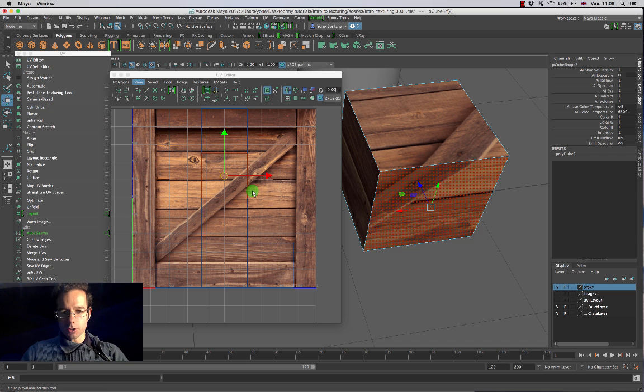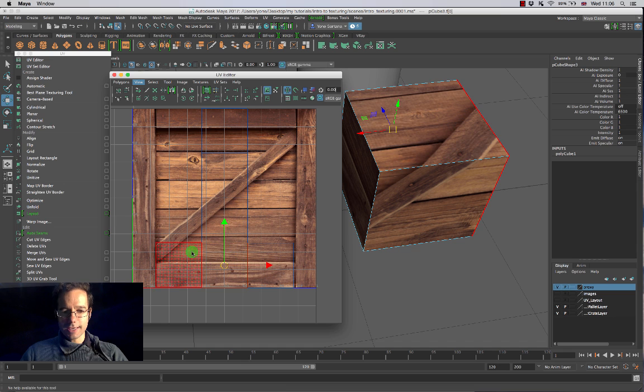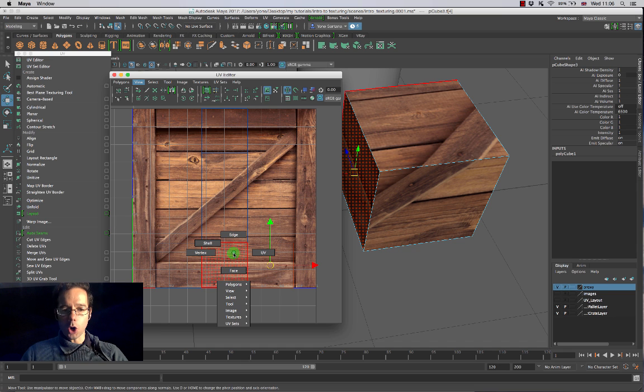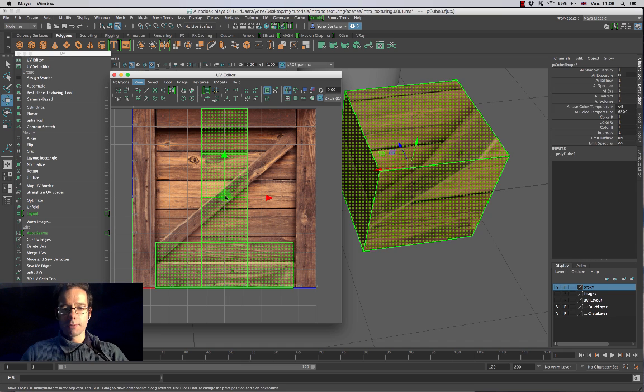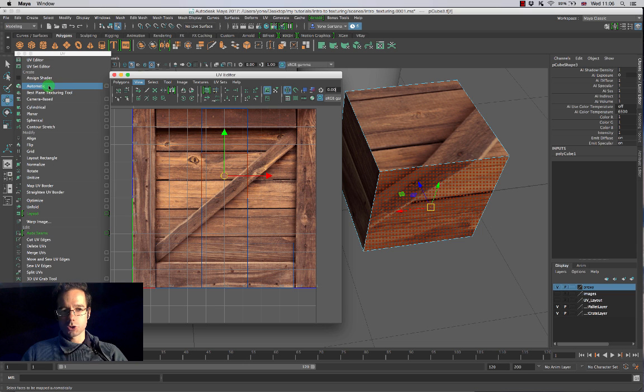So this little box over here, each individual face that I have in here, I need to tear it off the main UV shell. Before, I was cutting edges, and if I went into edge mode and selected cut split UVs, I could tear this out. But the projection modes have a big advantage, which is if I go into face selection mode over here and I select my individual face, and let's say I use the automatic projection.